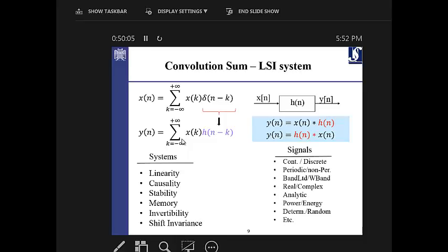It can uniquely be possible if this system is, later we will see, minimum phase. If this system is a minimum phase system, that can uniquely happen. So you're pretty sure that such a system you can find. But if it's non-minimum phase, then you have different alternatives. Probably you can find an inverse, but maybe that inverse is not unique.